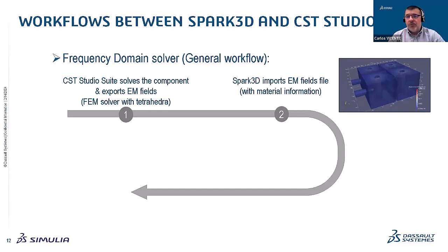I just want to note here that we have recently added in SPARK3D a task in the CST schematic. This way, the export and import of the file is not really required anymore, and the SPARK3D project can be part of the CST project. So the link or the integration is much tighter now.